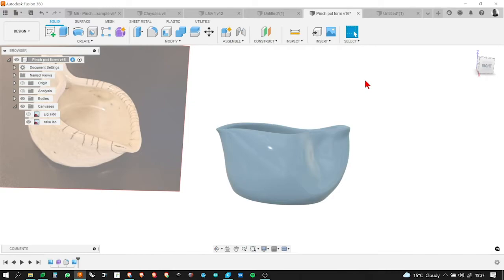That was my approach, but as I said before, with the sculpting environment, you can do it any way you want. I worked with a cylinder because I knew I wanted to make this a surface, because this has got a relatively even wall thickness, which I can then thicken afterwards. That was my thinking, basically.